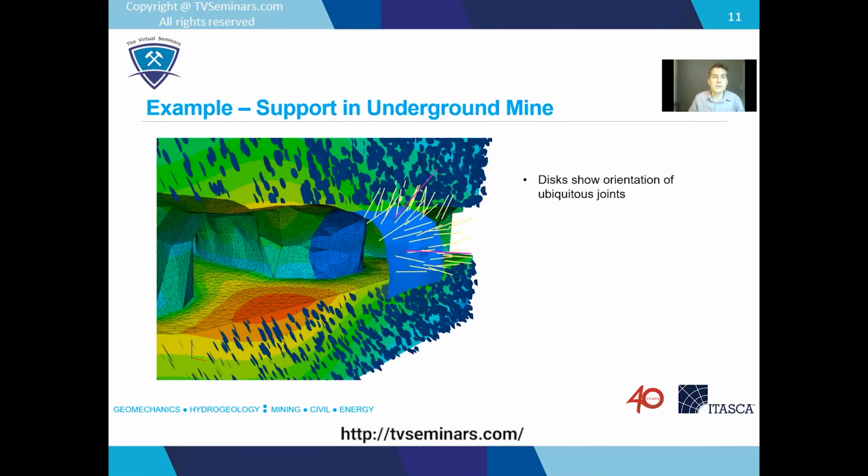So here's an example of the ubiquitous joint model. All these little blue discs here are not actually joints in the model. We're not actually modeling them. It's still a continuum. We're just making the continuum behave as if there was a bunch of little joints in here. And then you can get the displacements and stresses and so on like you do in a regular continuum model.